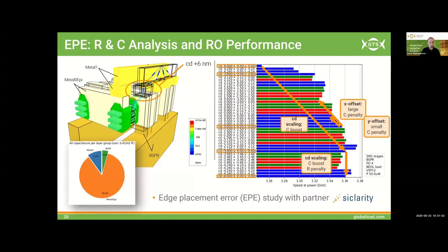So you end up really moving the detailed knowledge that you have from your 3D TCAD model and doing the variations on the layouts in an automated manner, generating quite a lot of data, but it also gives you insights. It gives you insights where you can see which of the parameters, of the margins, which of the design choices leads to what kind of impacts down the road on your actual performance, like here seen for this ring oscillator study.